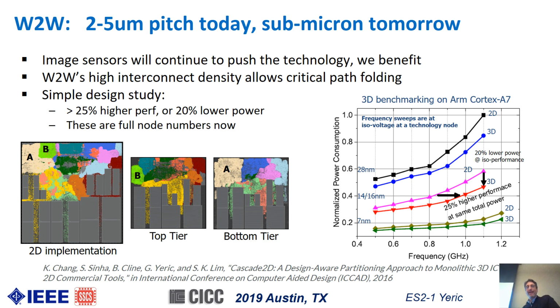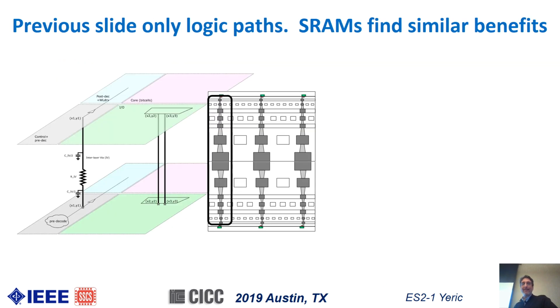So in that regard, it's really exciting, and it's virtually free. The stacking step is nothing. It's just taking 2 wafers, you stack them together. It's not expensive like building a FinFET or buying an EUV tool or what have you. One asterisk is you need 2 mask sets, right? So that is a cost up front. But other than that, it's a really, really attractive technology.